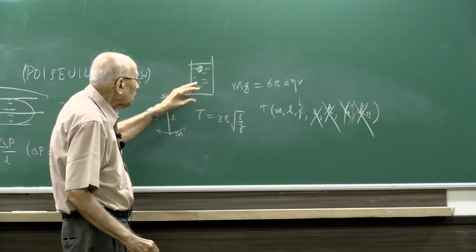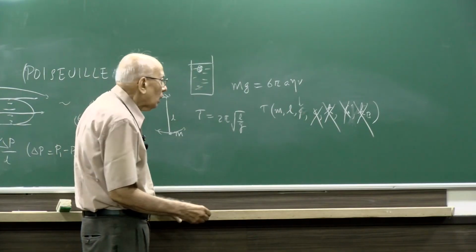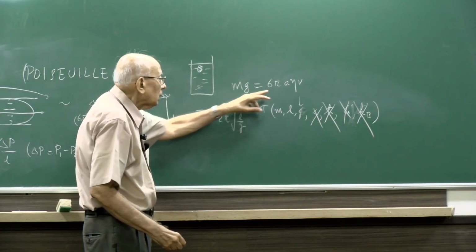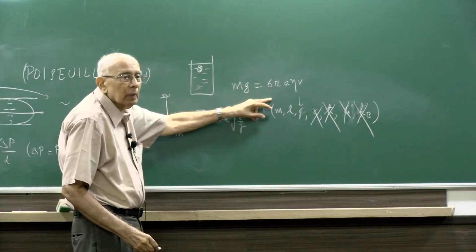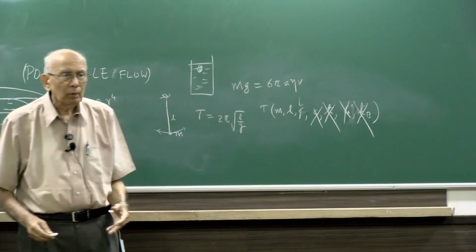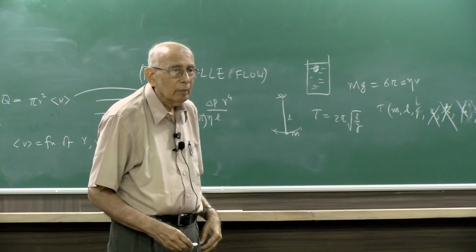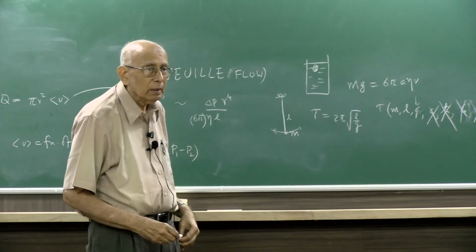On the other hand, if this was a superfluid, for example, then there'd be no viscosity. This would just sink straight down. It would be a slip boundary condition. This will become a 4 pi. If this were an ellipsoid instead of a sphere, it becomes some other factor and so on. For simple geometries, you can compute this factor. But that can't be done with dimensional analysis.